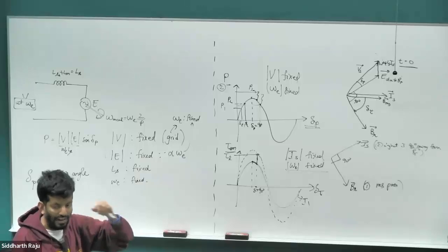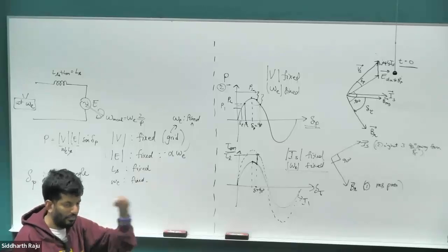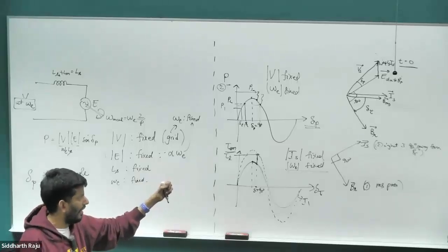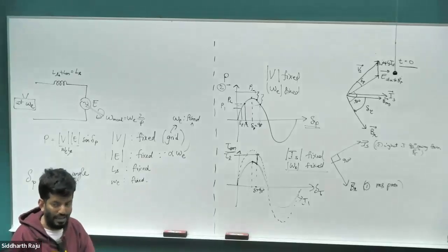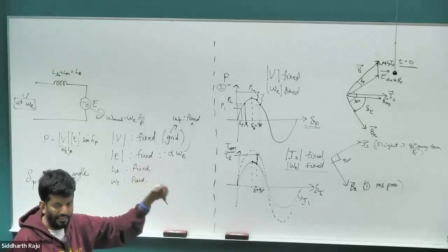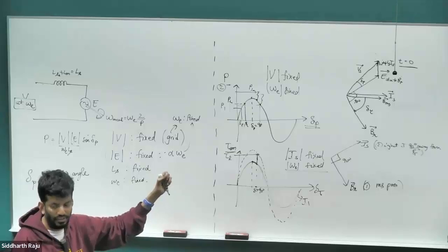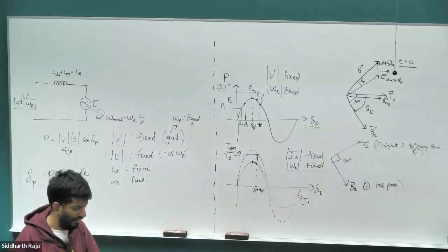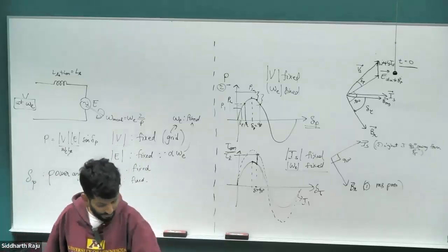When you apply an added load onto your electrical grid, basically this is the angle that increases. And even when you look at it as a motor, the same thing happens when you apply mechanical load on the motor. The rotor angle, the torque angle, starts to go behind, and that again starts to increase. And that's another reason they call that angle also load angle. The term is somewhat used interchangeably, which causes a bit of confusion.